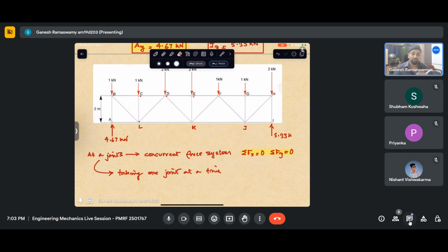Similarly, for the method of sections, if you cut a section through members and it reveals essentially three forces, in such a case you have three equilibrium equations at your disposal and you can solve it. So that is a determinate problem. In an indeterminate problem, if you are able to take a section which reveals more than three forces, but still you are able to solve with equations of statics, you may as well go ahead and do it. But those cases will be fewer, is what I'm saying. I don't know if I've successfully answered your question. If not, please pose your follow-up questions.